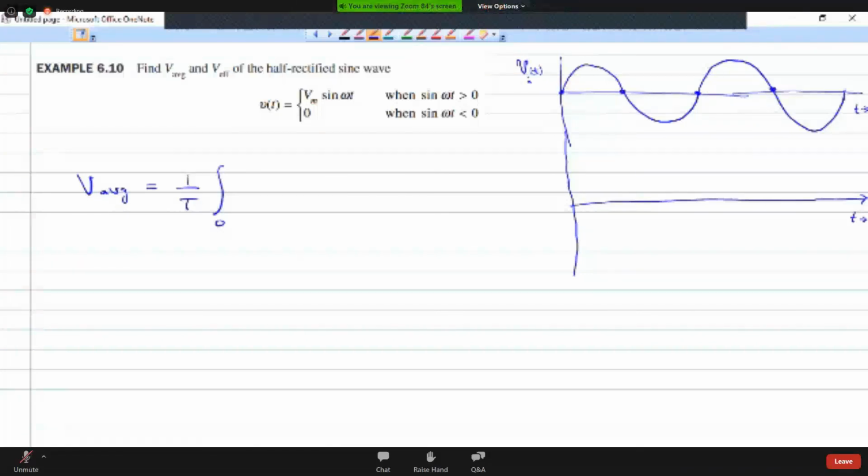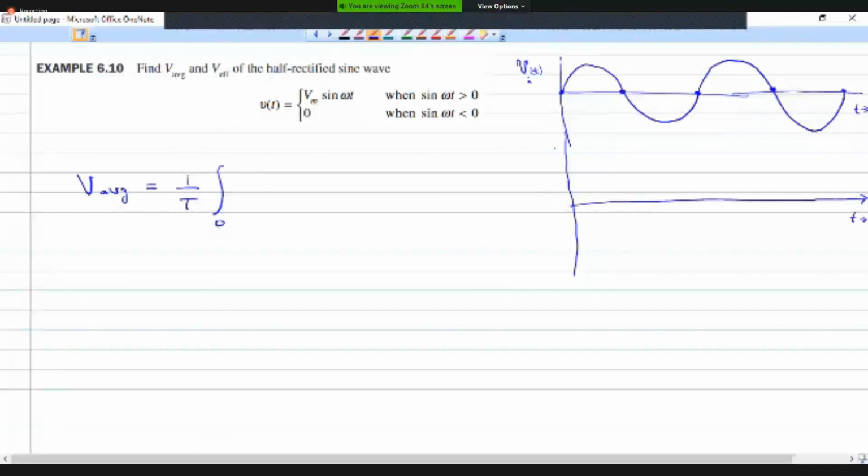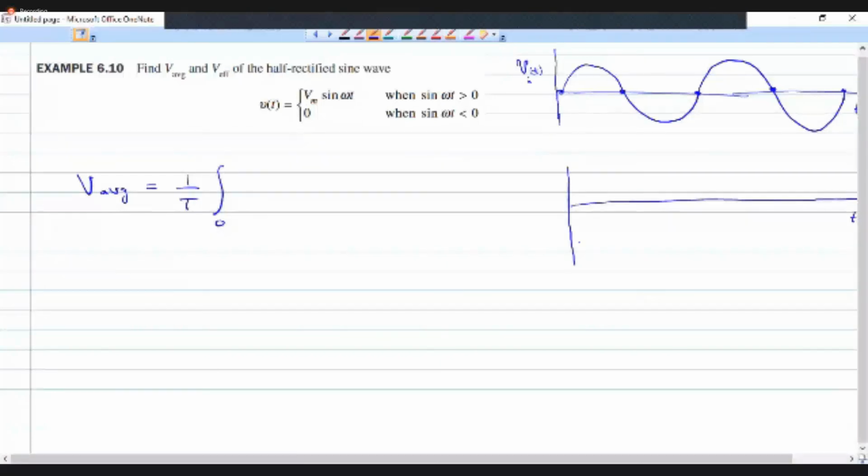So this is an alternating signal or alternating voltage. When we rectify this, there are 2 types of rectification we can do. Okay, one is called half wave rectification. The other one is called full wave rectification. In half wave rectification, what we are doing is we will only clip the negative part of the signal. Okay, so we will lose out that part. Okay, so let me use the same variable here, small v of t.